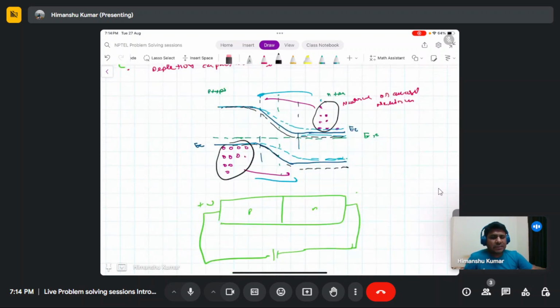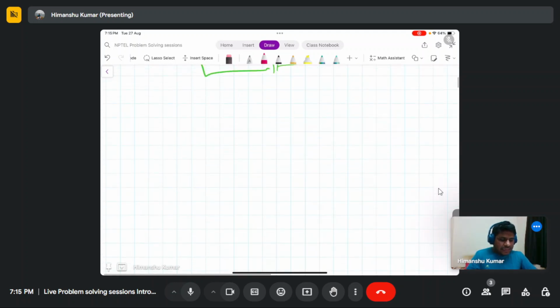So now what happens is, when you apply a bias, not all the electrons... basically, these electrons are going into the positive p side, and you can consider this as minority carrier injection. So these electrons are minority charges in the p region, and if you make an approximation, this tail is small, and the concentration of the n-type carriers injected into the p region is much smaller compared to the concentration of majority carriers in the p region.